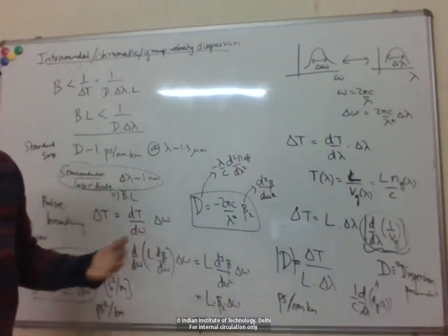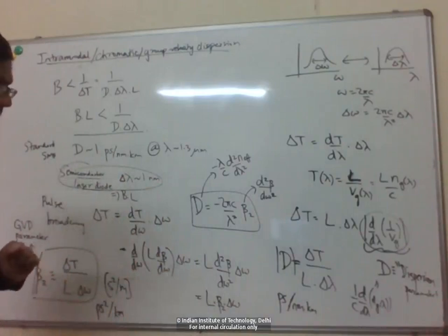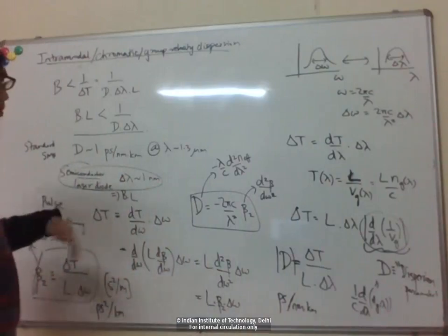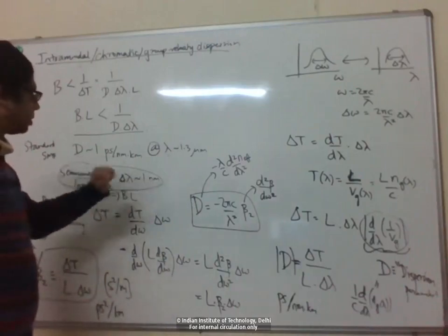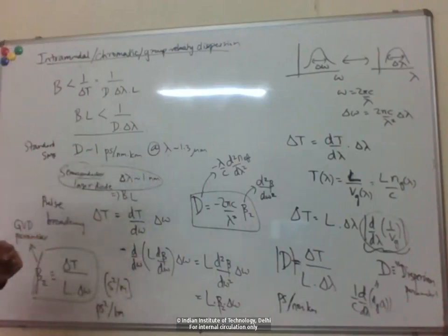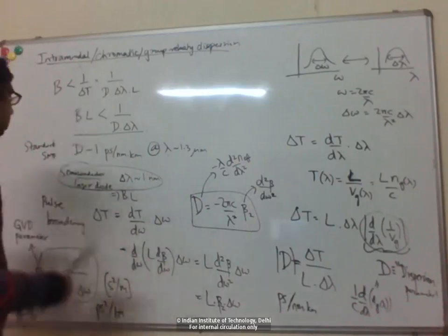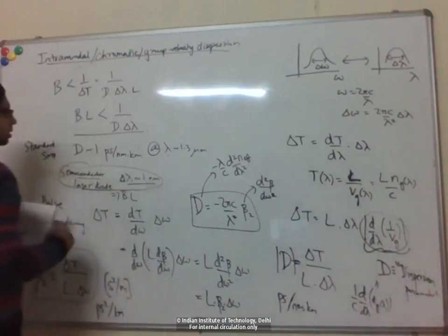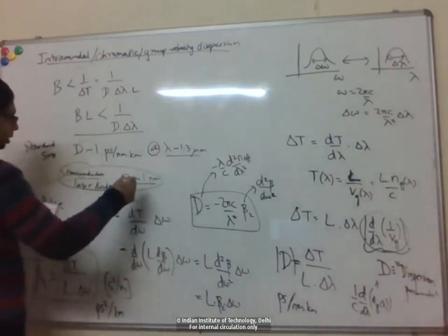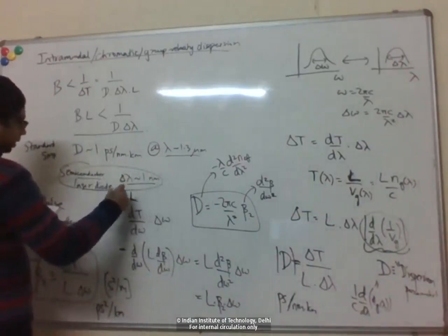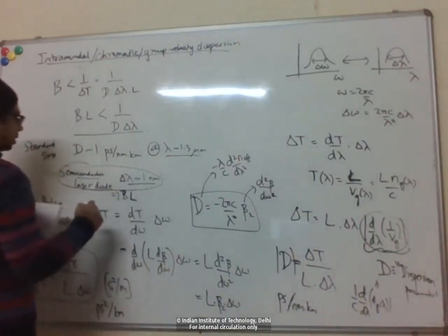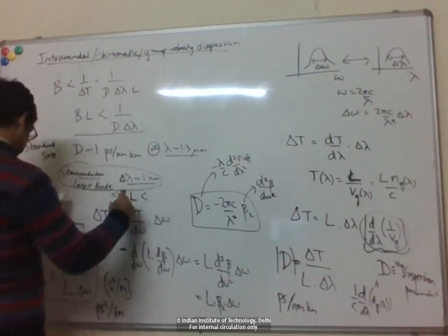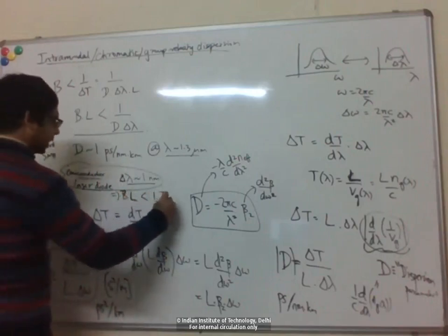Okay, so these are just simple laser diodes which are not stabilized using external cavities or whatnot. Nowadays, you can get single mode lasers where this delta lambda is much less than 1 picometer, so in tens of femtometer. So really almost single frequency. But anyway, even if you just put a reasonable or fairly high number by today's standards, the value that you get here is about 1 terabit per second kilometer.